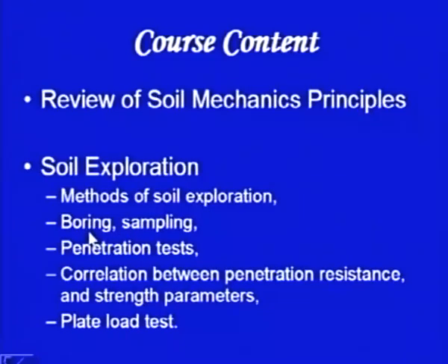So, I will be discussing the boring methods and how to sample them, and then we will be discussing the penetration tests. These are very important tests which are carried out in the field, specifically for cohesionless soils. Then we will discuss the correlations between the penetration resistance and the strength parameters. You get certain values out of these penetration tests, and we will see how to correlate them with the design parameters which we need. And then I will move on to the plate load test.